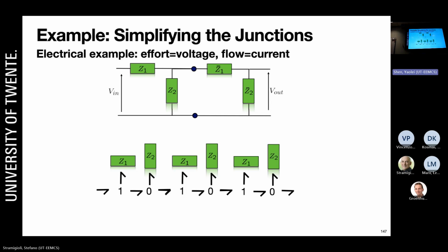But a wire, if you see it as a physical wire, with a section on this side and a section on this side, that's a two-port. On this point and this point. And inside, it could have a radiation, but at that point, there's a voltage and a current at that section of the wire. If you consider the wire thin enough, because if it's not thin, you have also a circuit of the wire in which you have different currents and different potentials. No problem, you go to fields, you can still do that. So it's all a question of modeling. Conceptually, what I'm saying here works all the time.